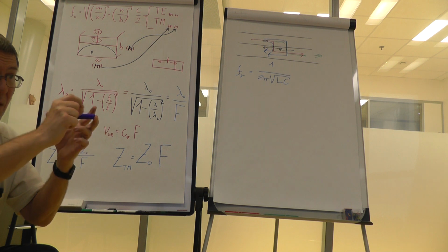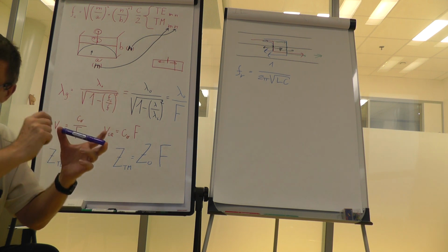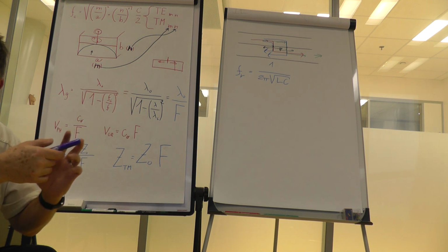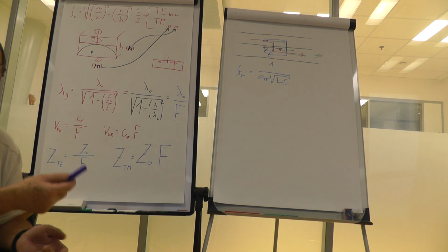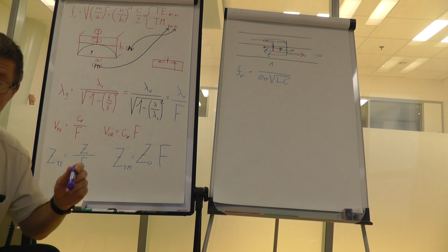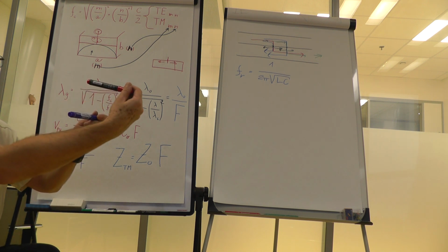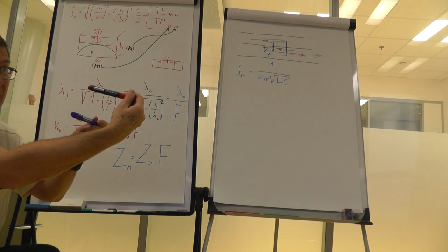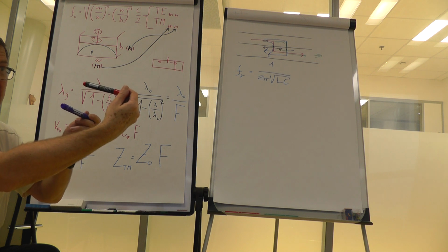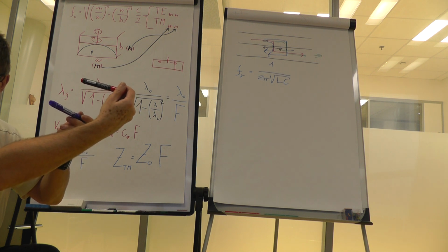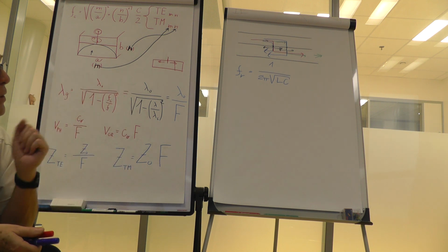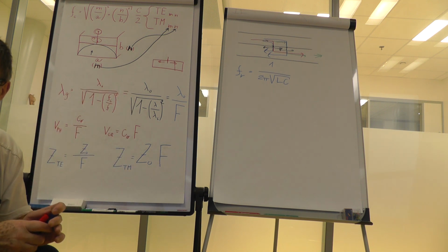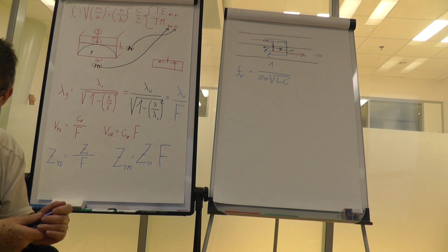It depends on the way you bend it and bond it at the ends, but let's say 1 nanohenry per millimeter. And if you just have two wires that perpendicularly meet each other, this arrangement would be close to a picofarad. Well, then you get into troubles with low values of inductance and capacity.